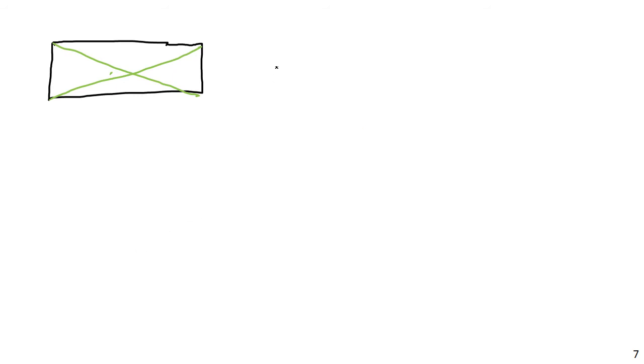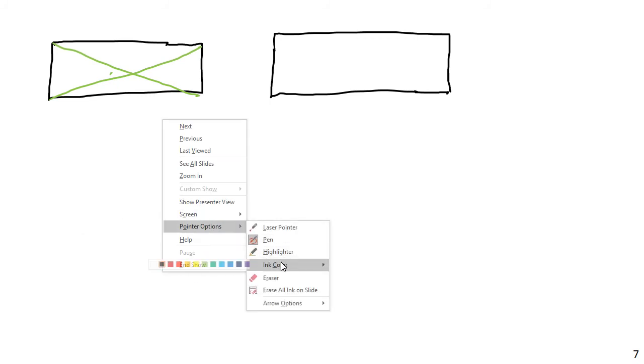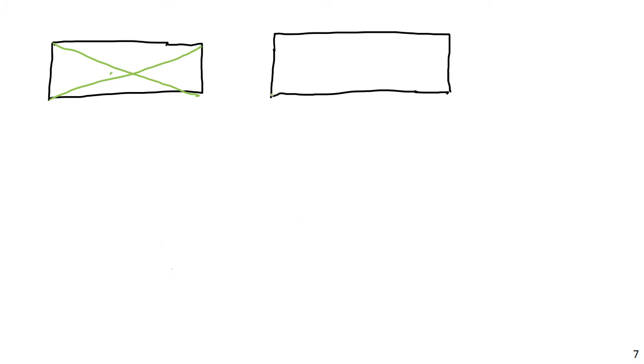What do I mean by that? If you want to divide a rectangle into trapezoidal loadings, you do the following. You start by going out at a 45-degree line from the corners. So you go 45 degrees out from the corners. Same here.